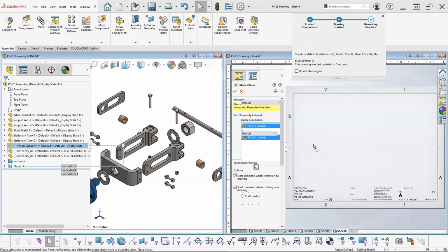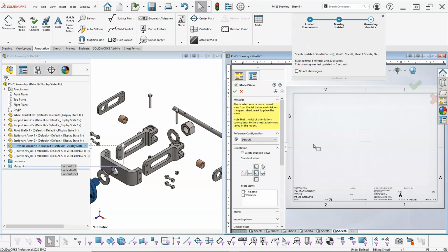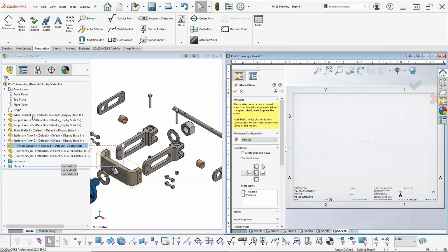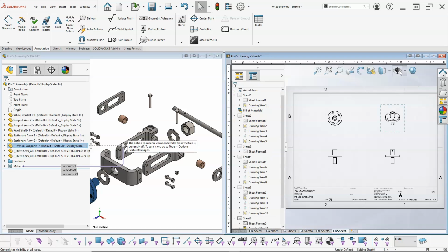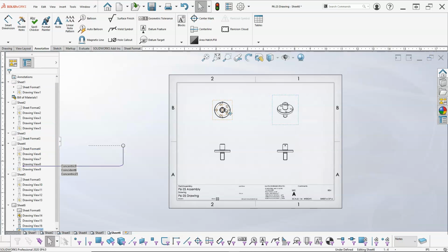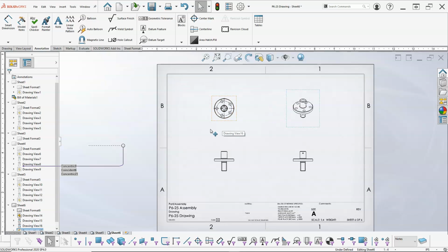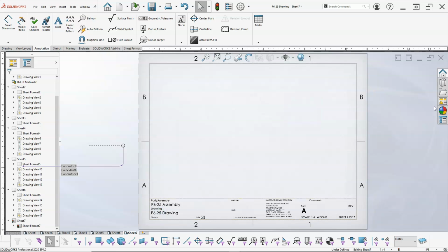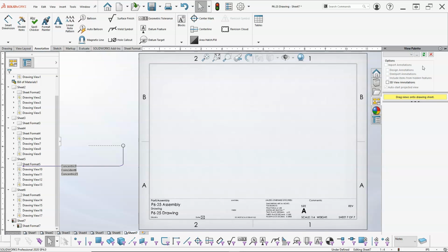So here's the advantages. I'm less likely to miss something if I go down through the assembly and I bring each of the items in. So except for the issue with the wheel bracket, let's go ahead and add those before I forget that. Except for the issue with the bracket coming in, we've got all of our components. It added my center lines, and we've got the group. So let's go ahead and we'll bring in these from the view palette and...